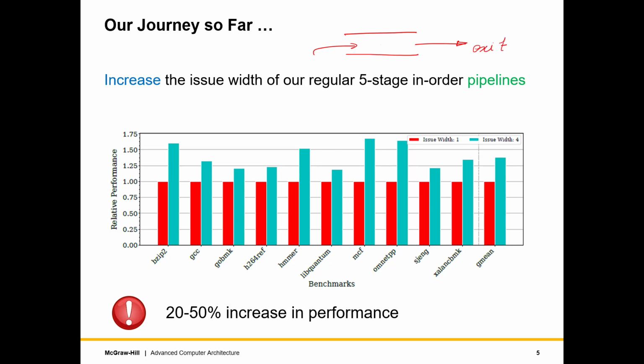If we consider this to be our basic structure, then we always have the option of issuing, which means sending down the pipeline one instruction or several instructions together. If we send several instructions together, of course, the dependencies between the instructions matter, and the additional scheduling and forwarding overheads are there. Nevertheless, there is a chance that the performance will increase, mainly because of the additional parallelism.